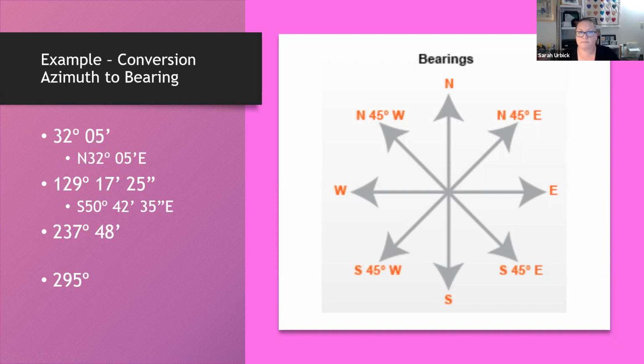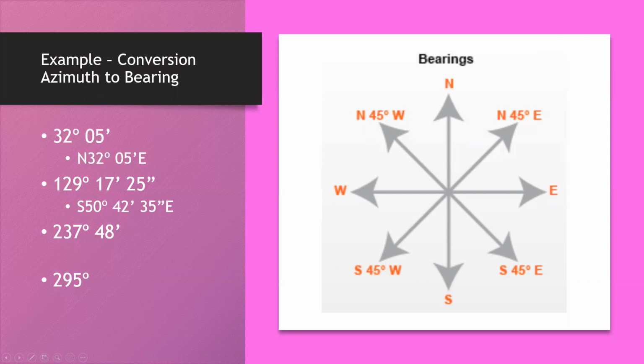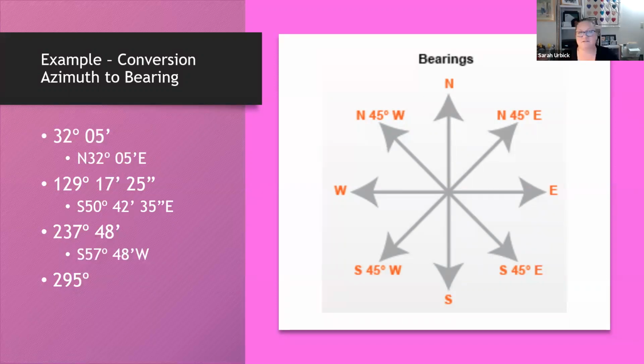What quadrant are we in? Third quadrant. So we're in the southwest corner. Would you subtract from 270? 270 is our horizontal. We want to measure off of our north-south. So I would want to find this angle here between my south line. Keep my finger off the mouse button.